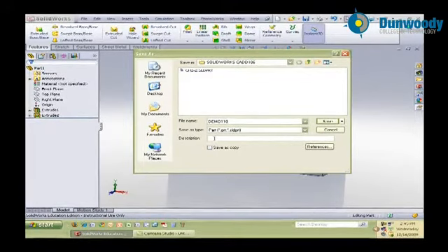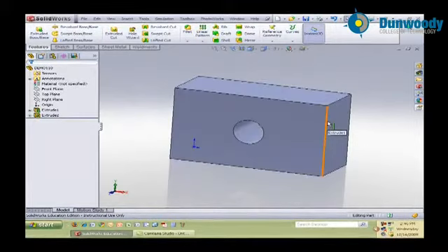I'm going to add a description to the part down here, and I'll just simply call it Block with Hole. And this will populate into my drawing automatically, so I won't have to do as much editing as I would have if I didn't do it this way. So again, part number is in File Name. The description of the part is Block with Hole. So I'll just save that. And unless I save my part, SolidWorks won't recognize it in order to put it into a drawing.